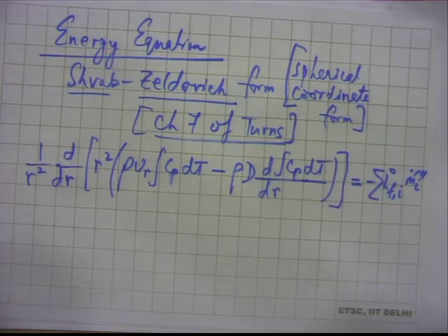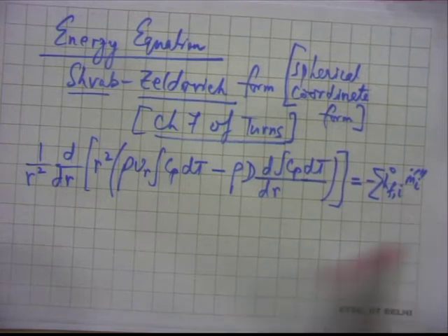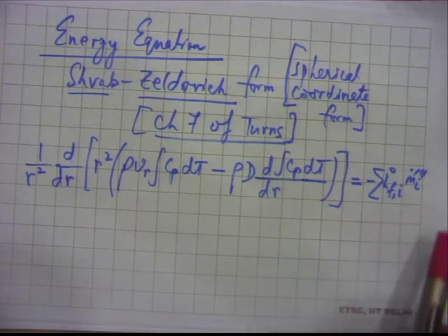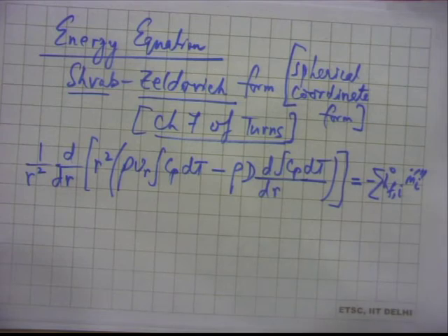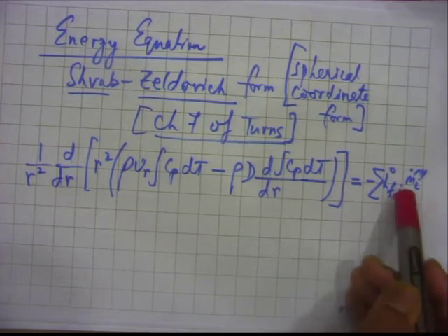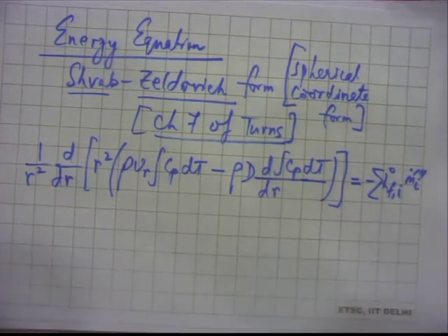Now, once we have picked this equation up, let's see what these different terms are for. What is this term for? This must be, yeah, so this must be the source term, isn't it? So it has an m dot i triple prime. That's the production rate of the ith species associated with enthalpy. So this must be the chemical energy source term, right?